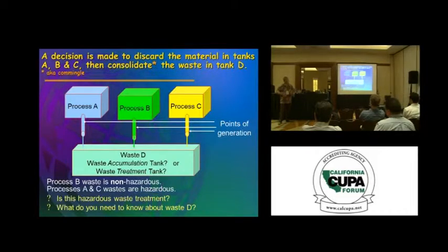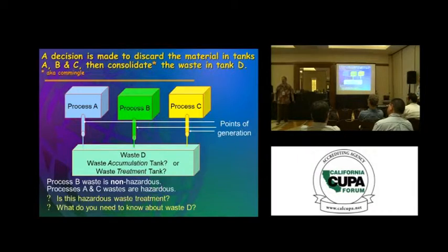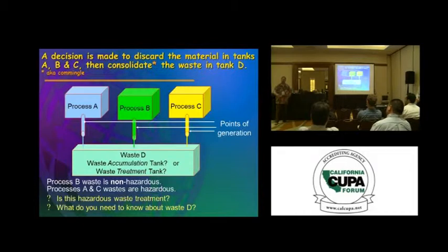Most of the time, maybe the treatment that actually happens in here would fall under conditional authorization or conditional exemption, for example. But maybe twice a month when we run the really good stuff, that would end up being permit by rule. So you really need to have a good understanding of the nature of the generating process and how variable versus consistent it is.